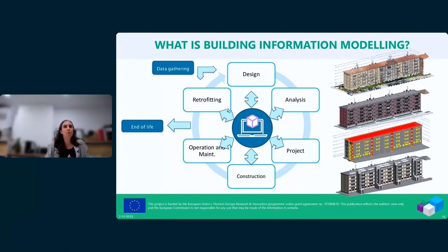In the case of the InCUBE project, we are working with existing buildings where renovation works are going to take place. Hence, our starting point is the data gathering of the current state of the building. In order to obtain geometrical information, we have been working with point clouds coming from laser scanning and UAV flights, as my colleagues will explain afterwards. All of the data contained in the model will be used in different project stages and will feed a dynamic digital twin.